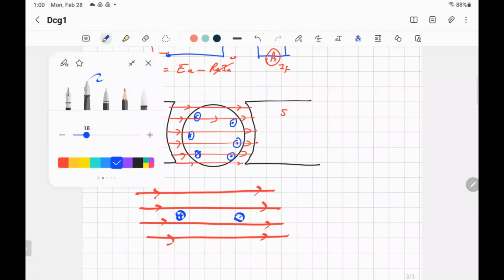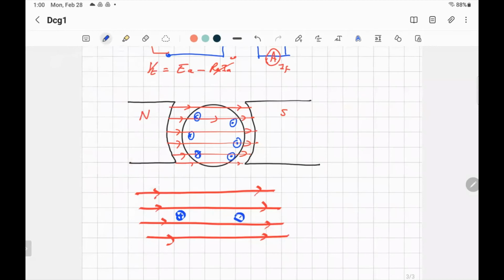So the magnetic field around this one coming in will be going in the anti-clockwise direction. So there will be magnetic field in this direction, right? And the other one coming out will be in the different direction. What is this blue circle? That's the magnetic field. There are many of them, but I'm taking only one for simplicity. But in the air gap close to the poles, I don't care about the middle. I care about the outside, on this side and this side, because I'm always concerned about the air gap. That's where the effect is.